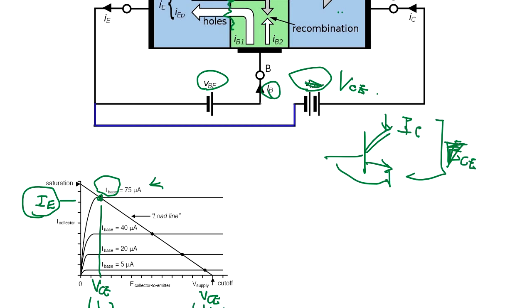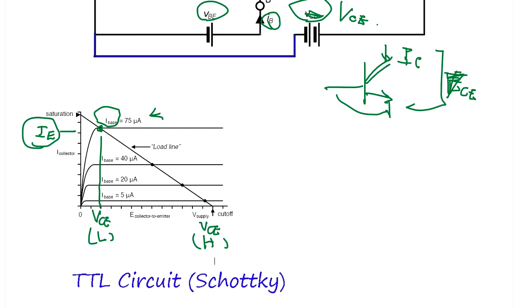When you operate in this range, it's no more transistor on and off. If you let too much current flow, this voltage goes down and gets into saturation mode. Once the transistor goes into saturation, it chokes off the current.